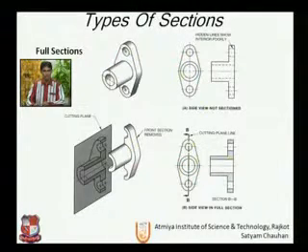If we cut this whole object, for example with the help of a cutting plane, imaginarily cutting through the center of these holes, it will cut into two parts. If we represent that cutting plane with B, and the direction will be that, the two parts will become totally mirror images of each other.